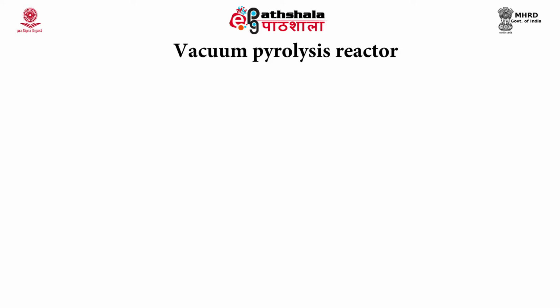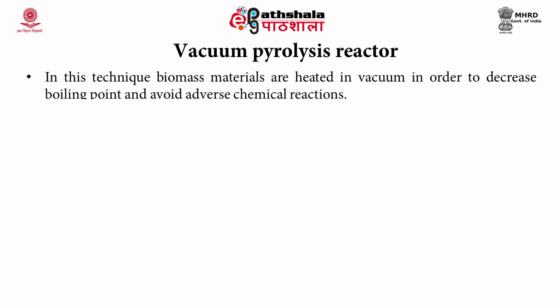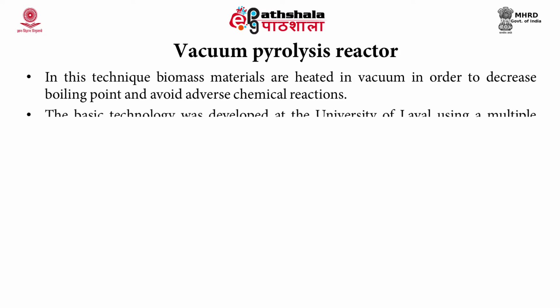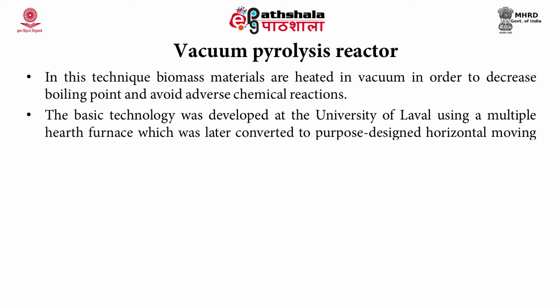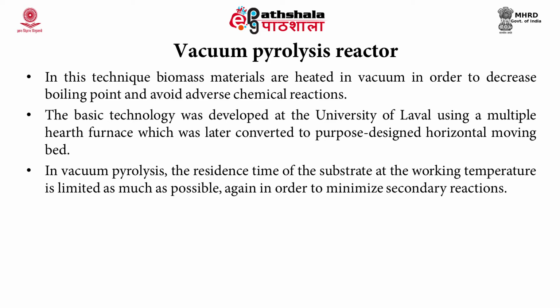And the fifth type is vacuum pyrolysis reactor. In this technique, biomass materials are heated in vacuum in order to decrease boiling point and avoid adverse chemical reactions. The basic technology was developed by the University of Laval using a multiple hearth furnace, later converted to purpose designed horizontal moving bed. In vacuum pyrolysis, residence time of the substrate at the working temperature is limited as much as possible in order to minimize secondary reaction.